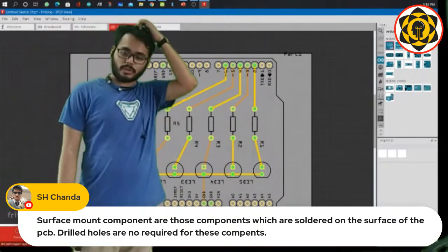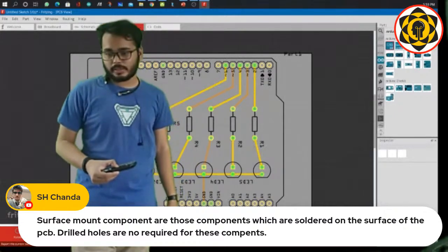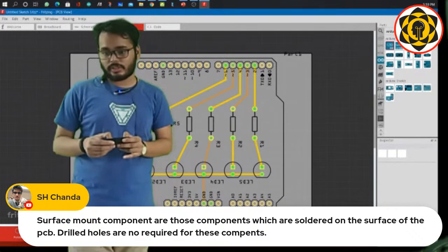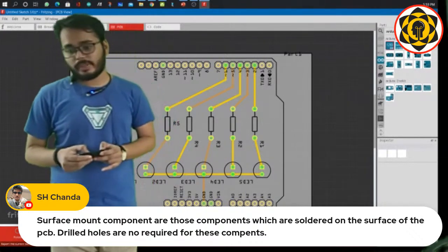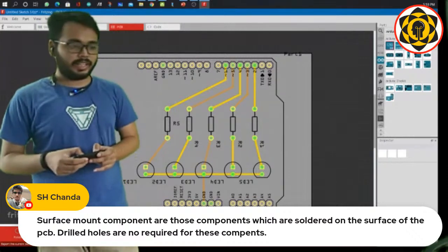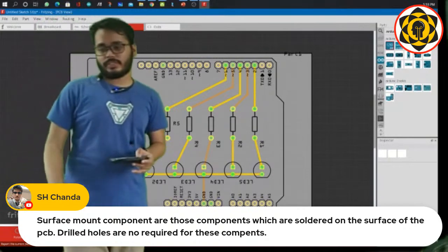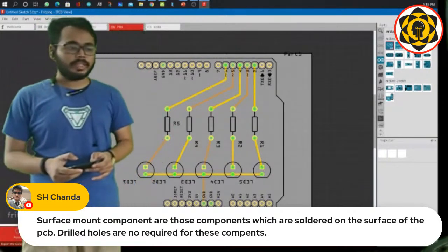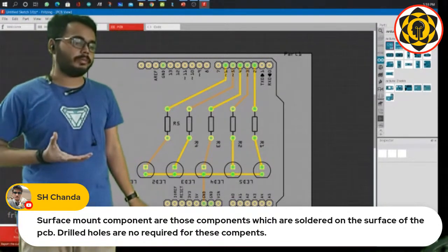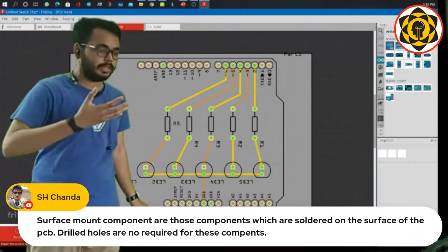So yeah, now all that is left is to export it. So let's go to export PCB, and now if we press on this small arrow right here, we get some options. So we can make etchable PDFs, we can use etchable SVGs, and we can use Gerber files. So let me tell you what each of these does. So etchable PDF is basically a format that you can use to build a PCB at home. Okay, so that will be our next topic. I will shortly show you how you can build a PCB at home.